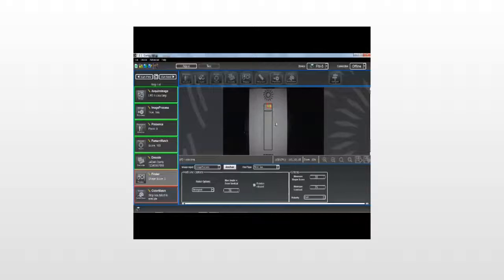And actually, I've got find line as the default set for the finder. What this arrow signifies is that the algorithm is going to search in this direction through the image till it finds a line. And you can see it found this edge line right here. But since I want to find this horizontal line, I'm just going to move this that way. And then let's move that to our line. I'm going to change my polarity of the line. I'm looking for the line to go from white to black. Let's change that. I'm going to tighten this area up a little bit.